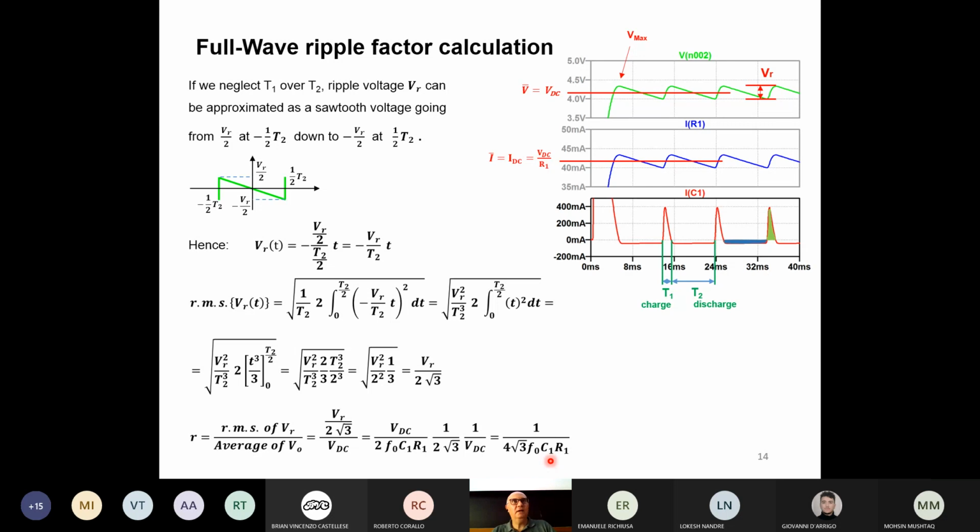When you study the switching power supply, you'll see that there are two big components: the capacitor and the inductor. If you increase the frequency, they both go down. So modern power supplies work at high frequencies and can be smaller. Obviously, the problem of electromagnetic interference becomes worse. That's for sure.